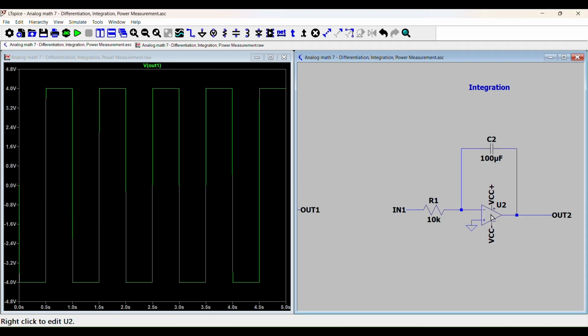The op-amp tries to invert that because it has to achieve Kirchhoff's voltage law. Whatever happens across here has to happen the opposite way across the feedback. And so the feedback is differentiating, the op-amp basically integrates. And then this network just sets the current that the op-amp integrates with.